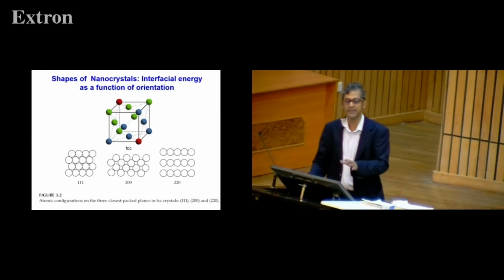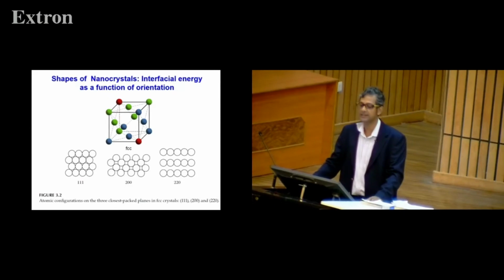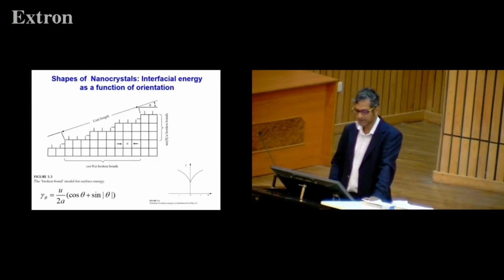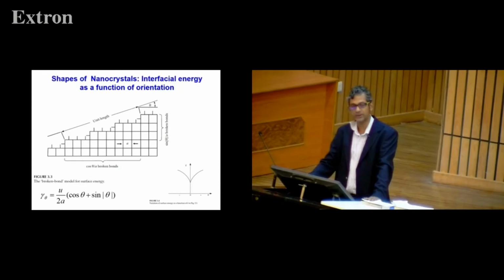Interfacial energy of any FCC crystal, for the sake of understanding, is different on different planes like 111, 200 or 220 planes. That means we can plot interfacial energy as a function of orientation, like theta, right? And this is what is shown. I'm showing you again and again so that you don't forget. Interfacial energy in 2D will depend on theta by the function cos theta plus sine mod theta. Please remember that.